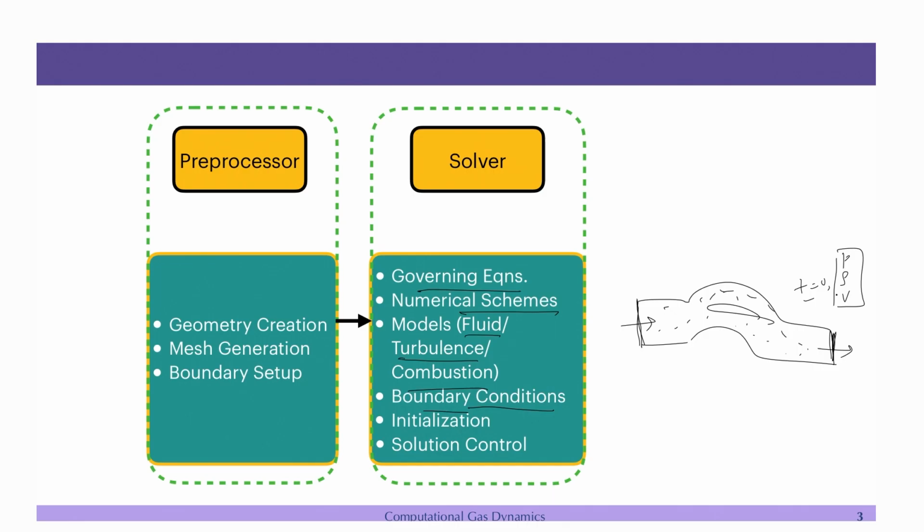These values usually do not change at the boundary, although there are time dependent boundary conditions also, but that you have to specify yourself. At the boundaries, anywhere on the boundary, you have to specify the value, or you have to apply, let us say, Neumann condition, where it will be extrapolated depending on what kind of flow you have.